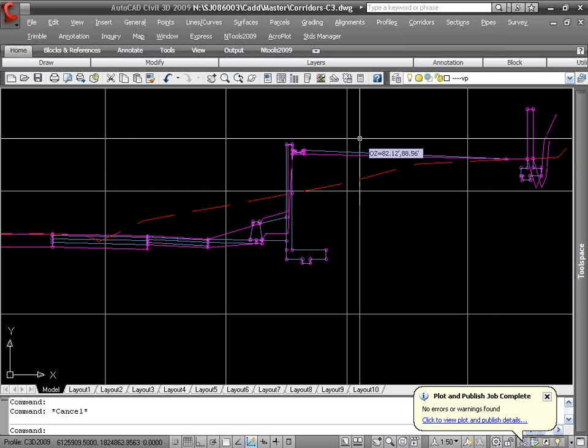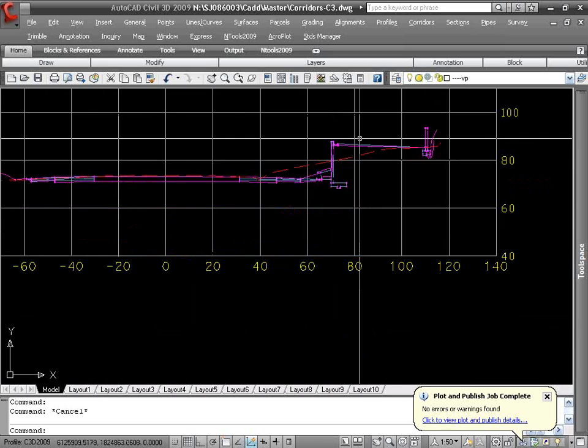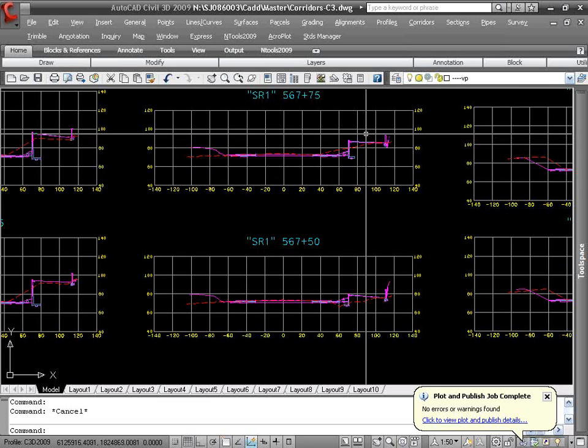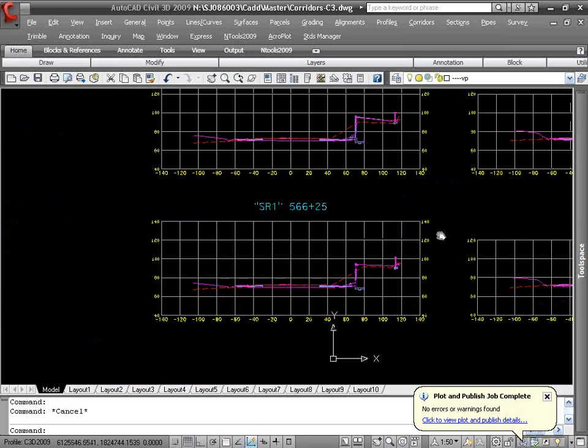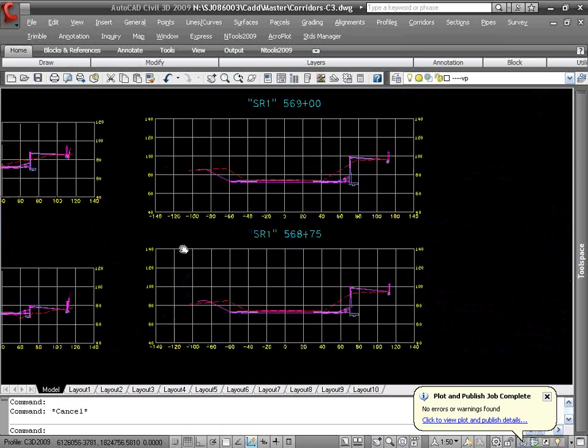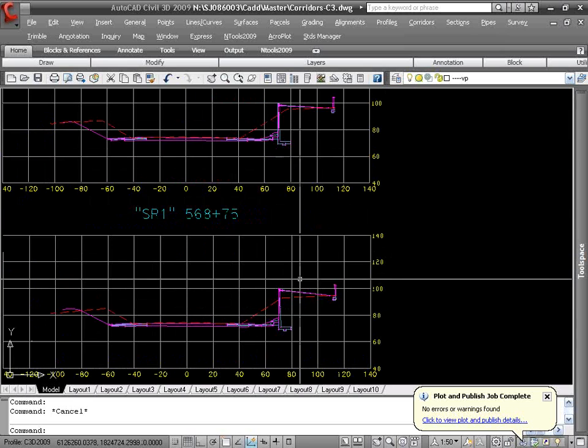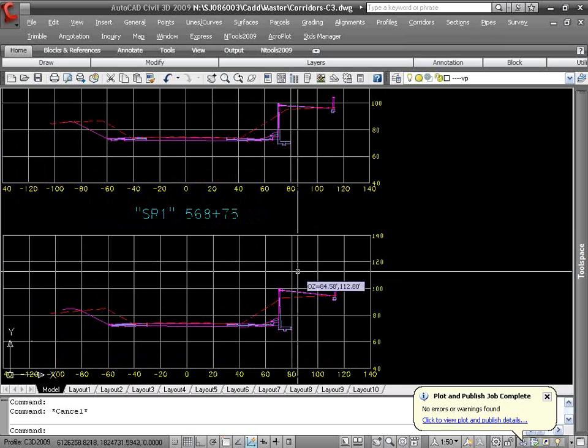Right now, we're actually working on getting the correct wall heights and footing heights. I guess Brandon had just put in a standard height for each wall, but now we're calculating all the different heights for each wall, and then we're going to go back and rerun these sections. I think probably the way we'll do it is by creating a finish grade profile for the top of the wall, and then just assign that. Apply it to the assembly. And then when we run the sections again, it'll find the top of each wall, and then it'll move it up or down.